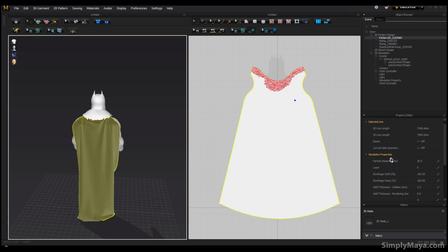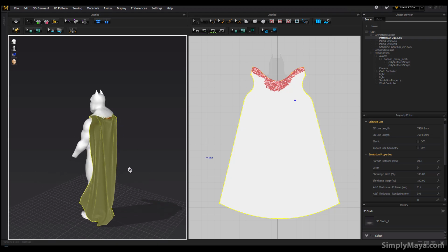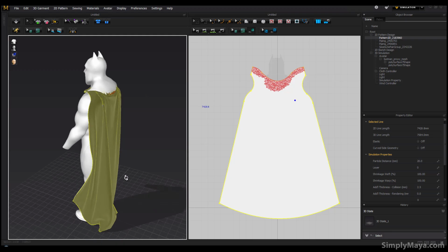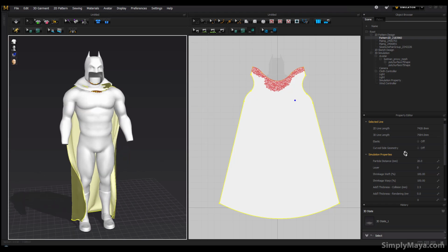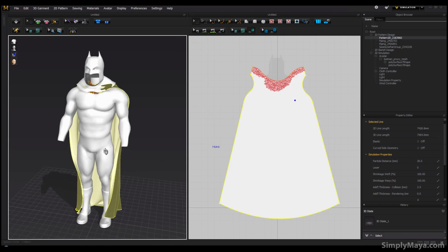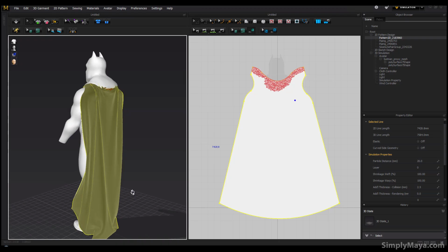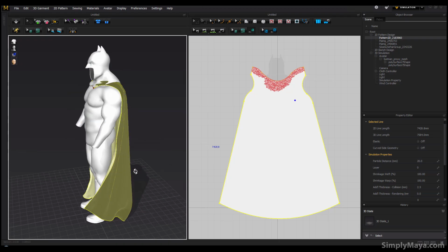The lower the particle distance, remember, the denser the mesh. So you're going to have to deal with that at some point. And also, the more memory, the longer the simulation process, the less easy it gets to pull around. So really I would wait to drop that particle distance until you've got what you're looking for, and what you're looking for then is just finer details and softer cloth maybe. But this is absolutely fine for me for demonstration.